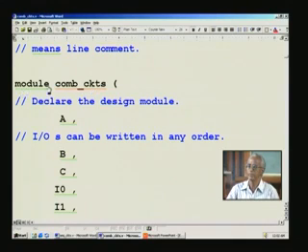And once again we see there is a module here, and the code might be a long thing. So you normally tend to forget an end module towards the end. If you forget, the compiler will tell you, and initially for beginners it may be difficult. So a good practice would be to put module and straight away endmodule and keep on keying in between things so that you won't forget. And once again we have braces here. There will be a start here and there will be an end brace toward the end, and we will have to declare all the IOs here.